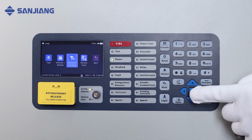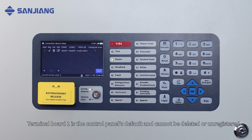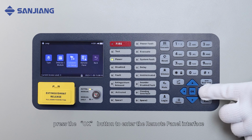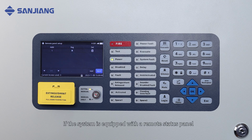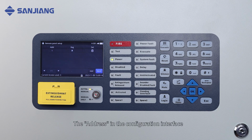Select Convention Setup. Press the OK button to enter the Convention Setup interface. Terminal board 1 is the control panel's default and cannot be deleted or unregistered. Select Remote Panel. Press the OK button to enter the Remote Panel interface. If the system is equipped with a remote status panel, it needs to be registered in the configuration interface. You can select Add, Register, or Delete operations using the arrow key and the tab key. The address in the configuration interface corresponds to the address of the remote status panel.